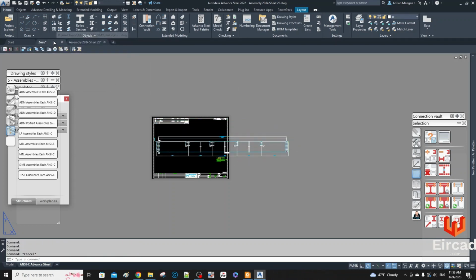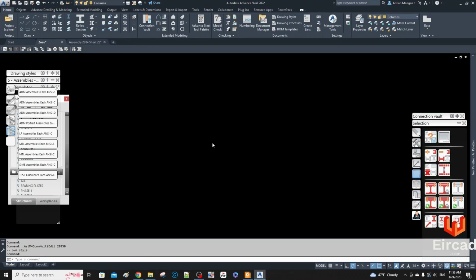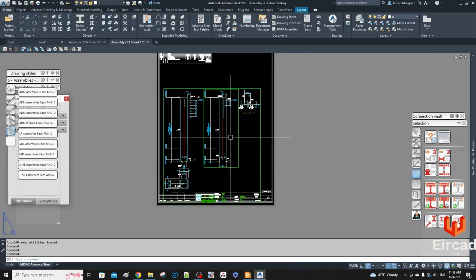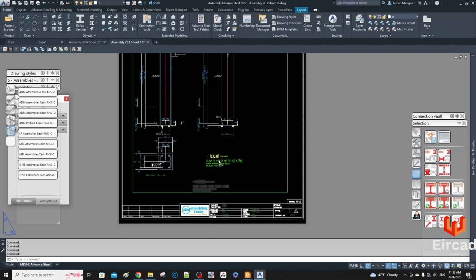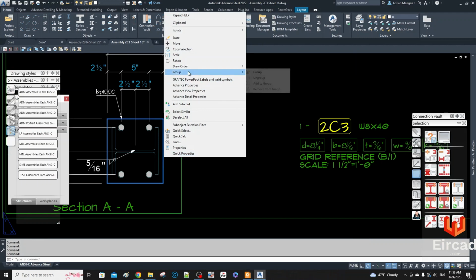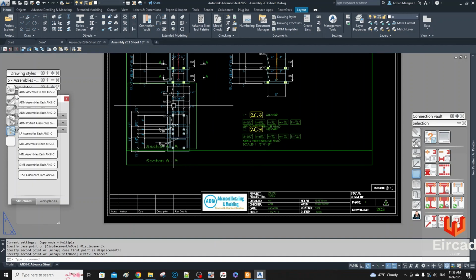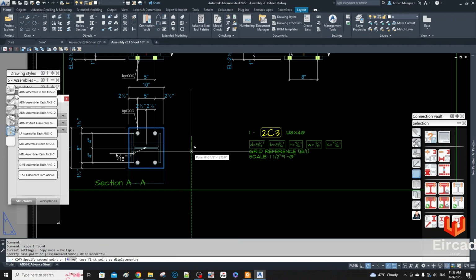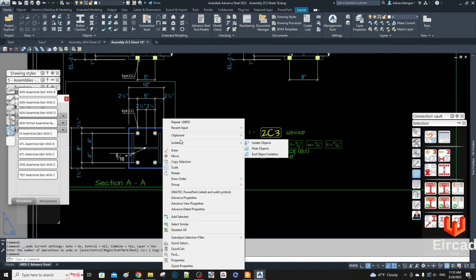And then if I go over here to the column and show assembly detail, it should be on a vertical or portrait sheet. And there you go, it's on the correct sheet. So now you have your two drawing processes. I shouldn't have done it the other way, because if you had just followed the first video, then your beams would have all been coming out still flat, but they would have been coming out on this sheet also. So just to have it on a different sheet, you have to use two different processes, and I don't know why I keep copying that instead of moving it, but anyway.